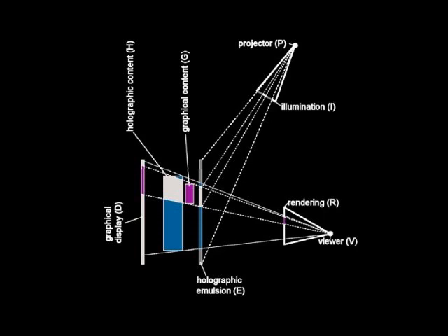Both reflection holograms and transmission holograms remain transparent if not illuminated. Thus, they can serve as optical combiners, leading to very compact displays. Graphical elements can then be integrated into the hologram from one side, while illuminating it partially from the other side.